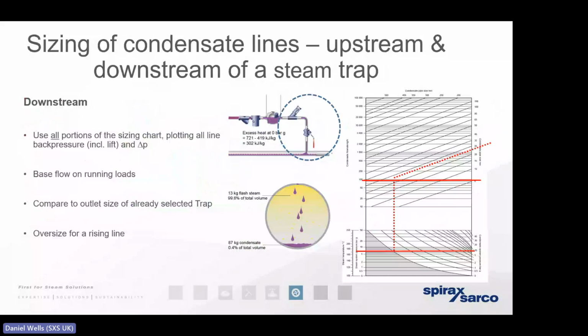And of course, that steam is going to expand by a factor of approximately 1,673 times. So we need to size the pipework downstream of the steam trap to allow for that biphase. The chart over towards the right-hand side of the screen really demonstrates that if we looked at the top of the two bold red horizontal lines, that pipework will be significantly undersized. Instead, we need to size on the diagonal dotted line to allow for that expanding biphase.